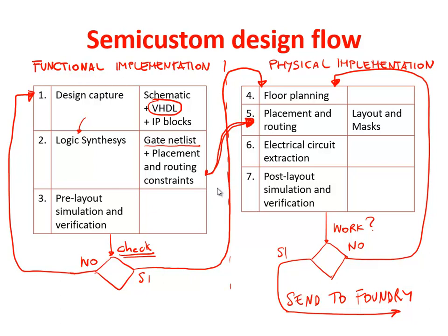So what is typically done is a post-layout simulation. From the layout, there is a software tool which makes the electrical circuit extraction. From the layout, this tool recognizes the different transistors and the different components, rebuilds the electrical circuit, so that one can simulate the circuit with a circuit simulator such as SPICE. So one can perform a simulation of the circuit extracted from the layout. And this is called the post-layout simulation.